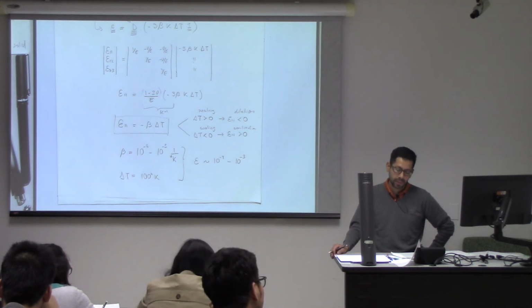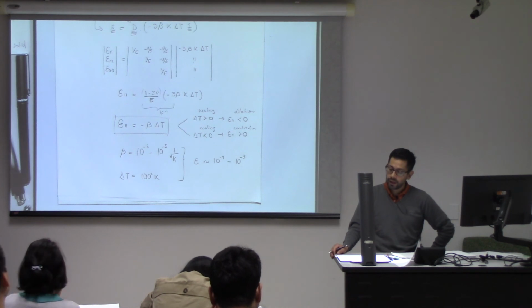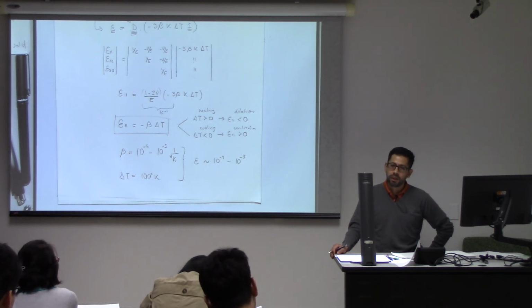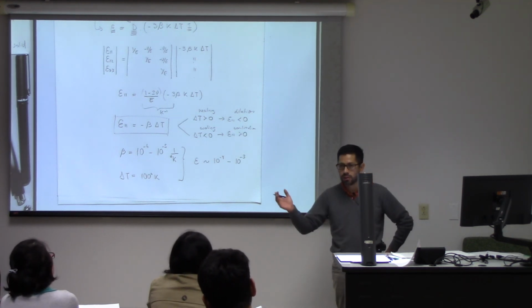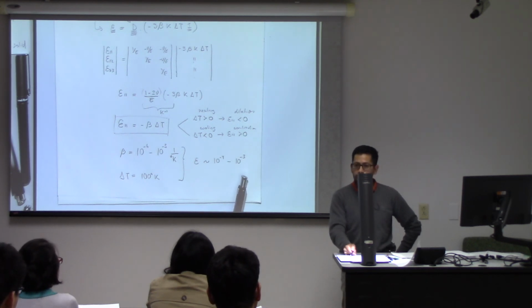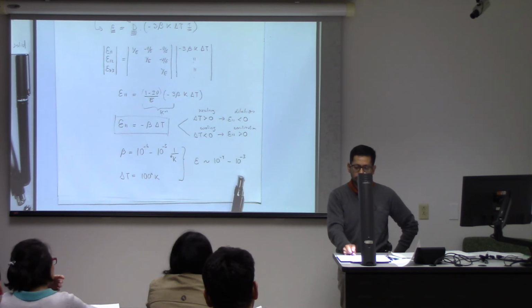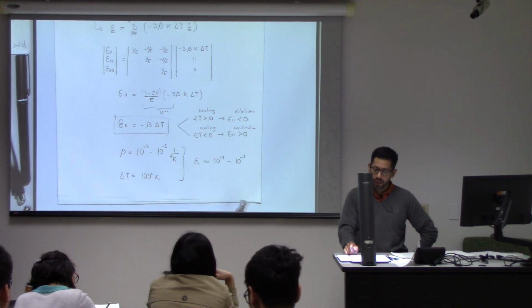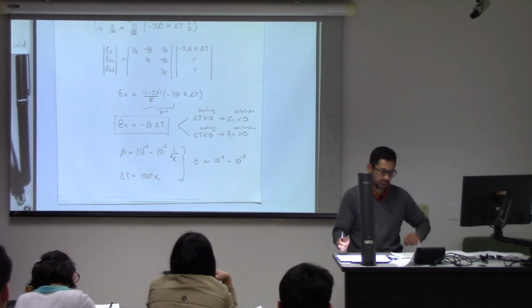It looks very small, right? 1/1,000 of a strain. It seems that it's not much, but actually it is quite a large strain. For example, with waves, sometimes you have very small strains, 10 to the minus 6, 10 to the minus 7, 10 to the minus 5. 10 to the minus 3, especially for rocks, is very high. Probably for soils, it's not a lot. But for rocks, this strain can cause significant changes of stresses. And that's what we're going to see right now.